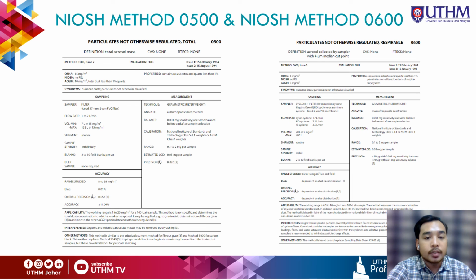The method is routinely used for collecting all kinds of particles from metal shavings to pharmaceutical dust. The NIOSH 0500 method is a default method for dust sampling in this study. In other words, if you need to collect the dust and the sampling procedure is omitted from the method, by default it is the NIOSH 0500.